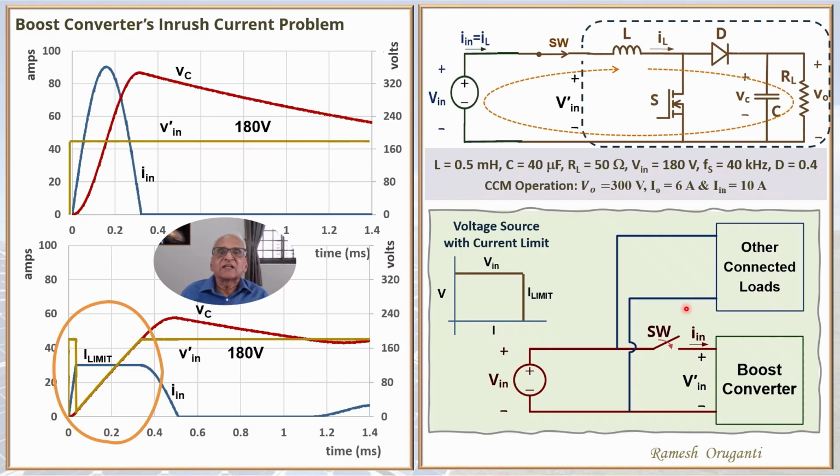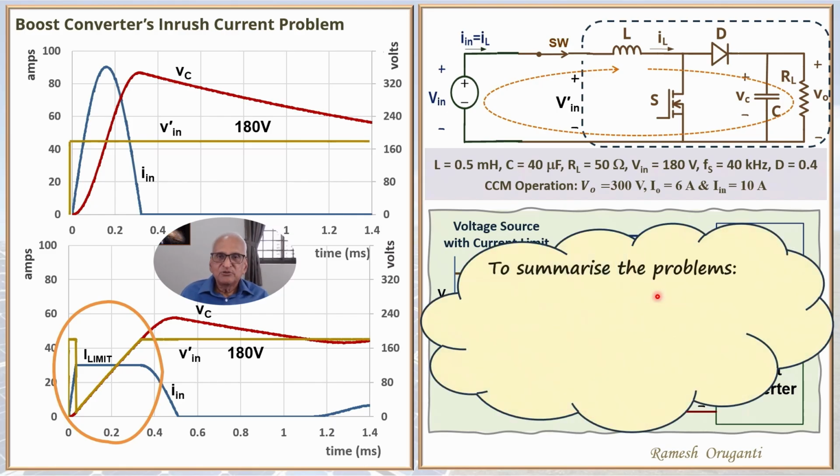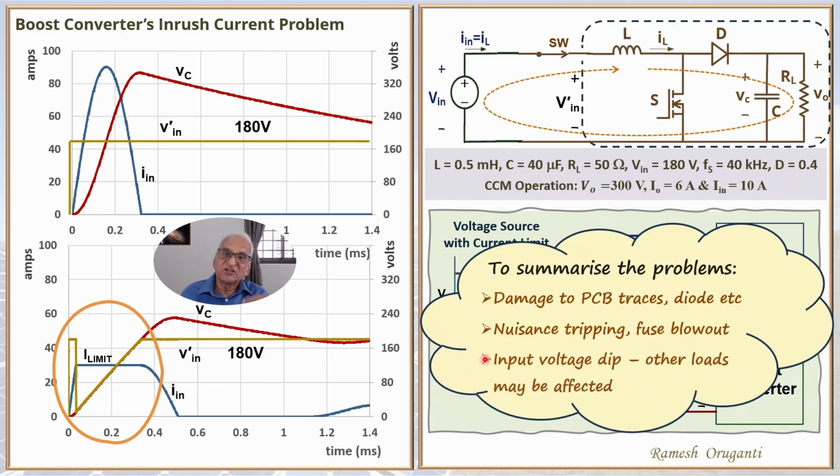and that might affect other connected loads. To summarize, damage to the PCB traces, diode, etc., nuisance tripping, fuse blowout, and the third one, possibility of input voltage dip affecting other electronic loads, particularly when you have current limited source feeding the boost converter.